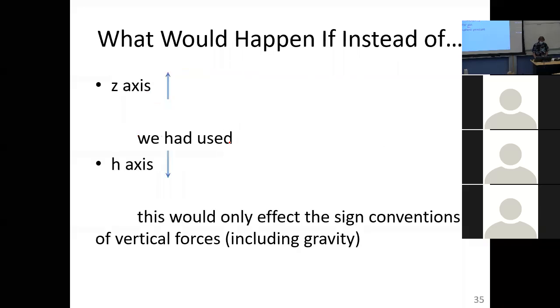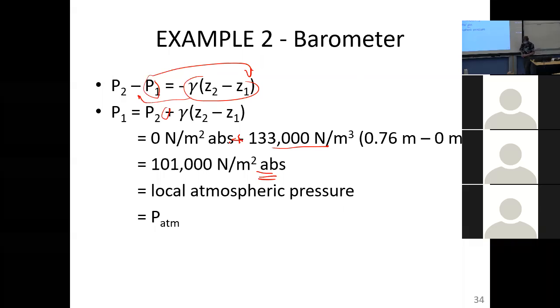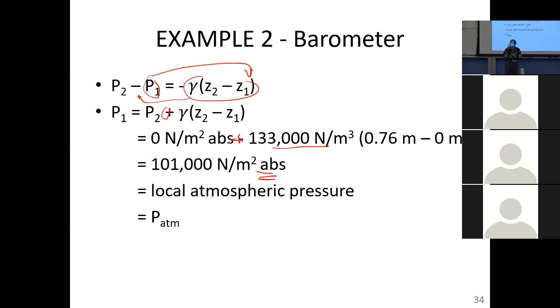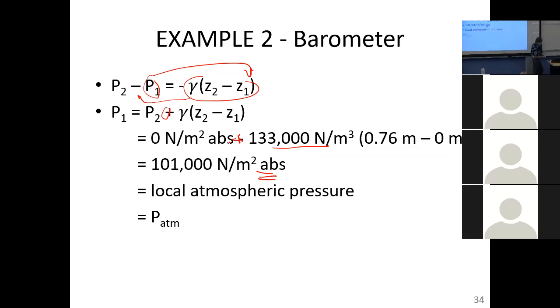And commonly, again, we can have devices. So we'll use pressure transducers, for example, to measure wave height. When we throw that pressure transducer into the ocean, we'll tie it to a cinder block, throw it in the ocean, and then we'll be measuring the water level over it. Since the pressure transducer is not vented, we have absolute pressure being measured. So we need another transducer above the ground measuring the atmospheric pressure. When we subtract the two, we get the wave height, the water height, which is the class before us, coastal measurements.